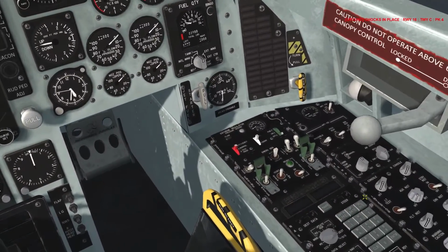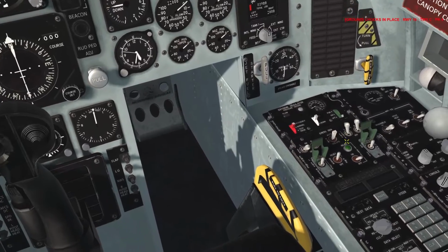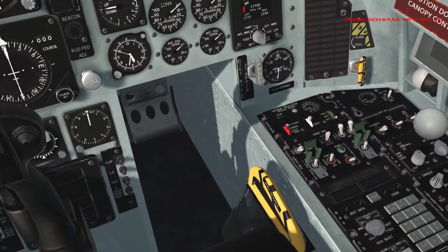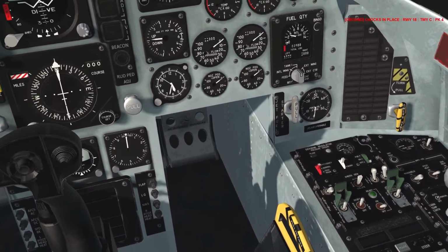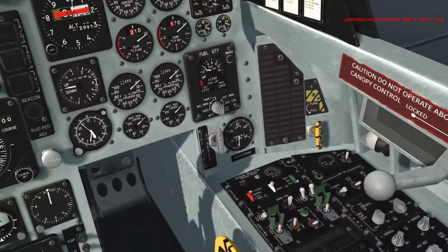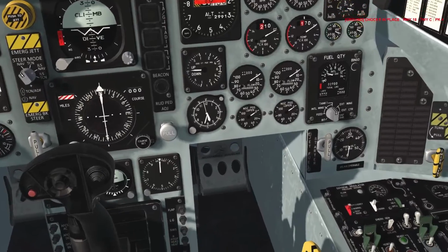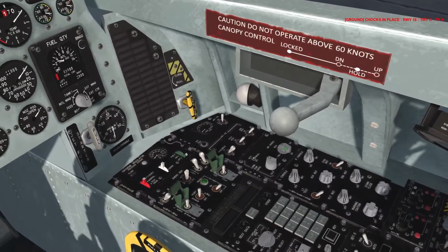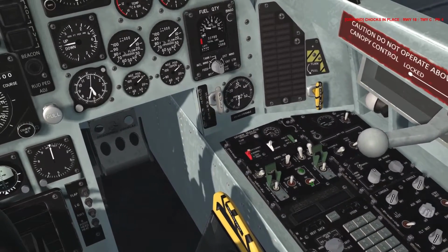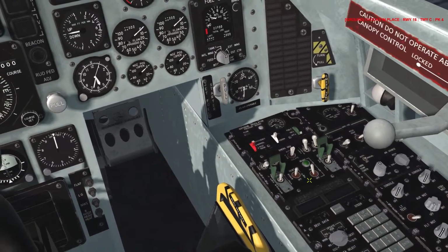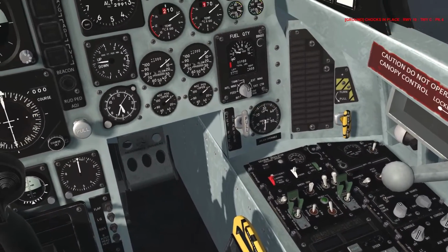Anti-ice switches off, the avionics off, which is as they are set per the cockpit interior check. So engine starting, we've got air source to both, the JFS start switch to on, and the JFS handle pull and release.